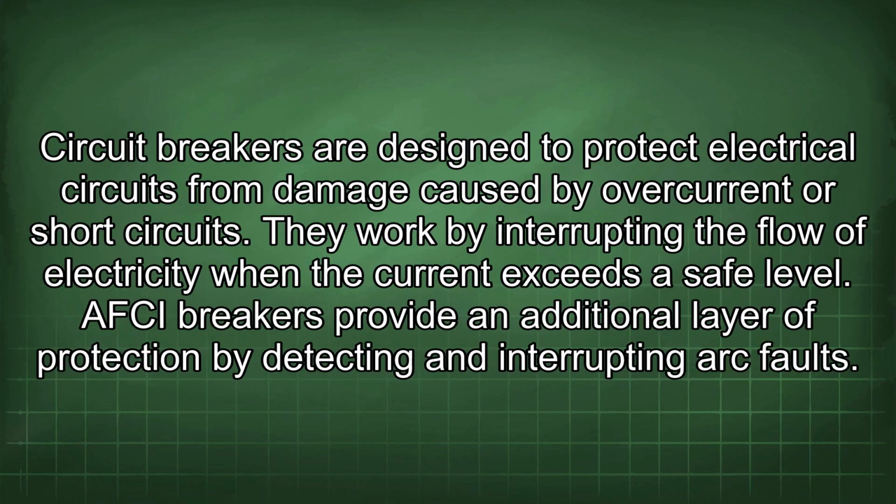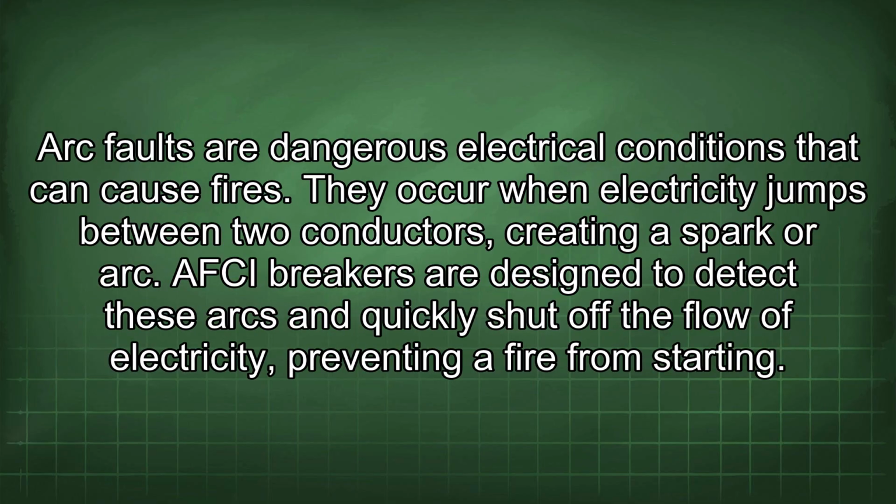Circuit breakers are designed to protect electrical circuits from damage caused by overcurrent or short circuits. They work by interrupting the flow of electricity when the current exceeds a safe level. AFCI breakers provide an additional layer of protection by detecting and interrupting arc faults. Arc faults are dangerous electrical conditions that can cause fires. They occur when electricity jumps between two conductors, creating a spark or arc. AFCI breakers are designed to detect these arcs and quickly shut off the flow of electricity, preventing a fire from starting.